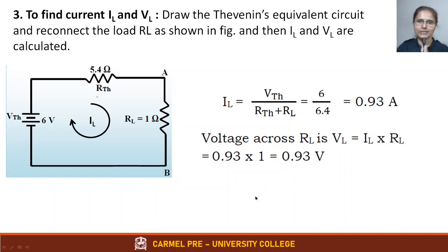So this is how you solve the problems using Thevenin's theorem. Understand the concept. Any complex circuit can be replaced by a Thevenin equivalent circuit consisting of a simple circuit, that is a voltage source called VThevenin in series with a resistance called RThevenin. That is the Thevenin equivalent circuit.